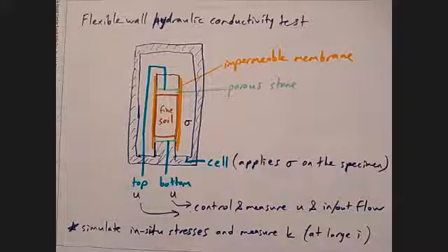But then the question is, is that enough? Because hydraulic conductivity isn't like any mechanical test. In a mechanical test, if some part of your soil is weak and the other part is strong, the strong part is still going to carry the loads.